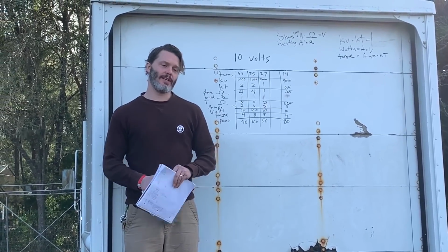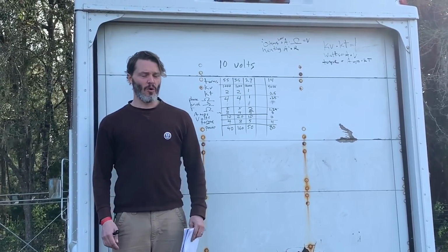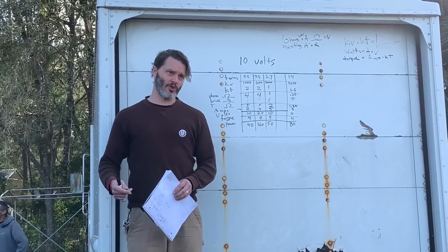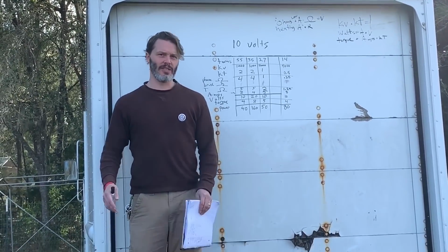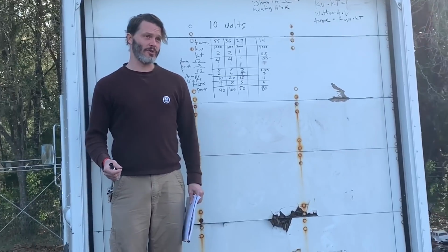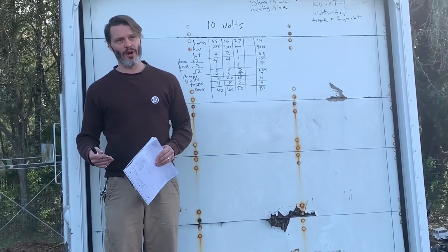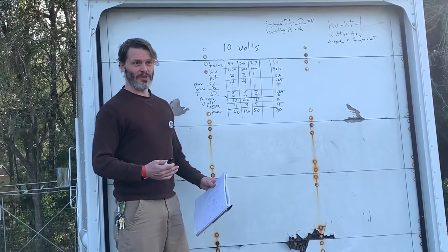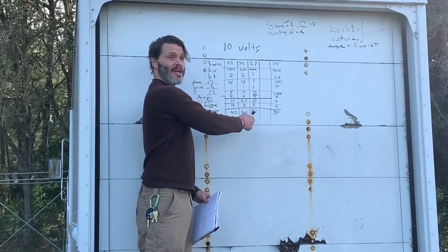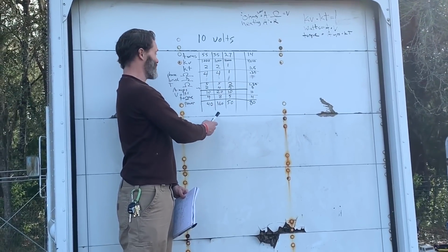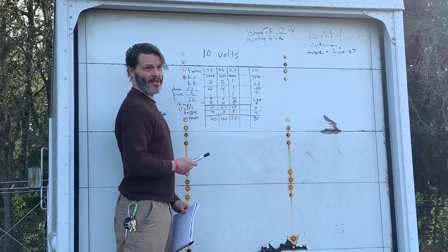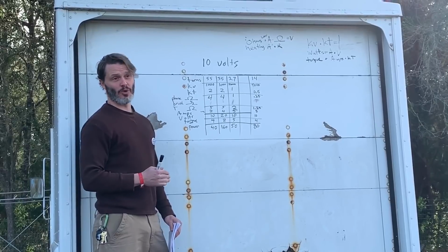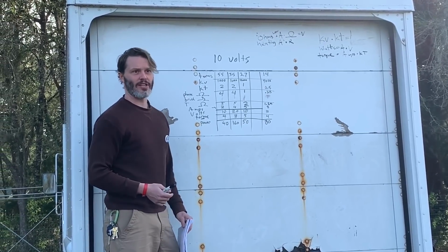Absolutely, and that's like considering a 2-pole versus a 4-pole, or a 5-slot motor like the Crawlmaster versus a 3-slot motor, which would be a Trailmaster, Torquemaster, and pretty much everything else in the market is still 3-slot. So 3-slot motors are going to be a lot more torquey, they're going to have more drag brake, and they're going to have more pop off the line. It's not going to be as controllable. The easiest way to describe the difference between them is when we're at this 2000 kV range, a 3-slot motor is actually going to have a lower phase resistance by a little bit, about 20% or so. Whereas a 5-slot motor has a little bit more resistance to it, but you gain a slower startup. And that is the more tractable, the more controllable power.